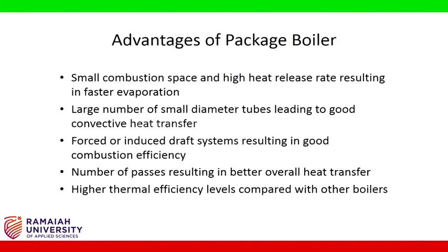Small combustion space and high heat release rate, resulting in faster evaporation. Large number of small diameter tubes, leading to good convective heat transfer. Forced or induced draft systems, resulting in good combustion efficiency. Number of passes, resulting in better overall heat transfer. Higher thermal efficiency levels compared with other boilers.